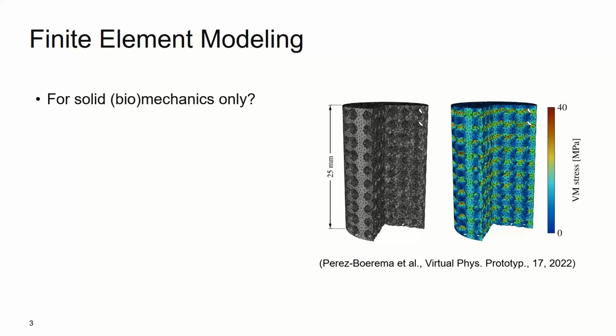So as I said, when we talk about finite element modeling, these are the simulations that people usually think about. You have a structure, you mesh it, you divide it into elements, and then you apply some loads and boundary conditions, and you want to get some stresses or deformation out of it. And this is actually true. This is still finite element, but it actually has a broader meaning.